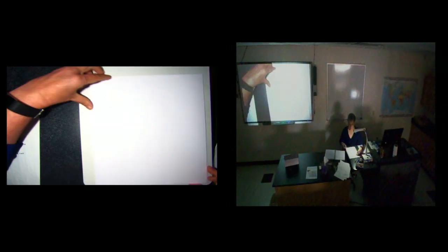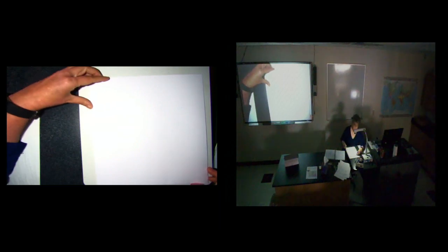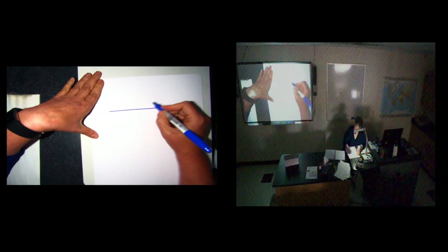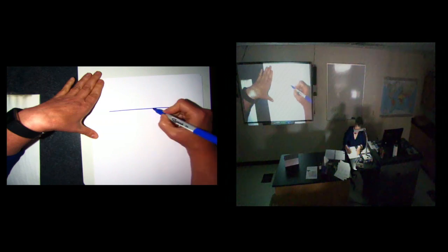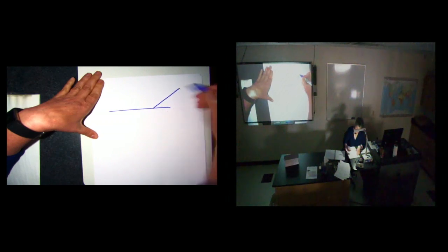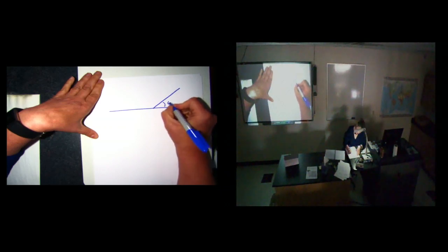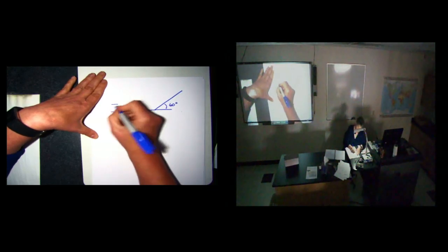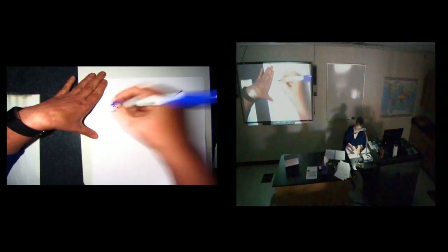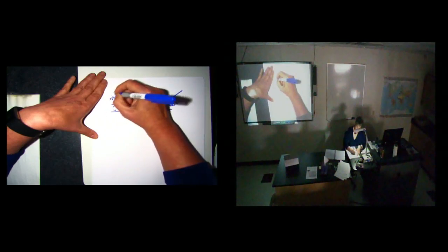I can find the velocity at B in the y direction, and that's going to equal the initial velocity in the y direction minus gt. That's going to be 75 sine 45 degrees minus 32.2 times my 1.887 seconds, and this is going to give me a negative 7.684 feet per second.